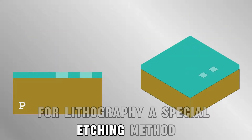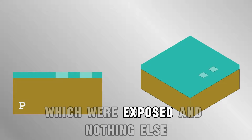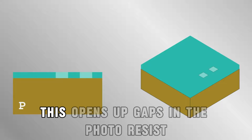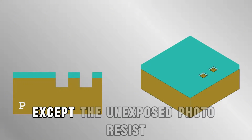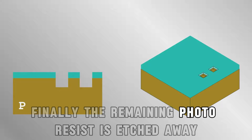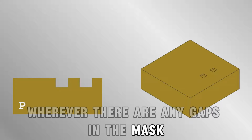A special etching method is used to remove only regions of photoresist which were exposed and nothing else. This opens up gaps in the photoresist, and then another etching method is used which targets everything except the unexposed photoresist. Finally, the remaining photoresist is etched away. As a result, material has been removed wherever there are any gaps in the mask.